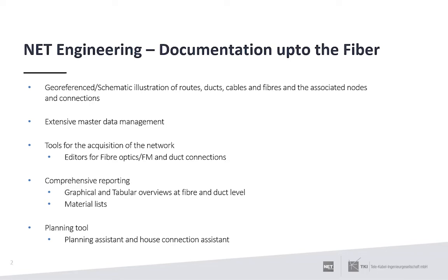You could expect tools for the documentation of the network, such as the connection editor for fiber optics or telecom cable, or the duct connection editor. An extensive reporting with graphical and tabular overview on fiber and duct level gives you an overview of the captured network. A material list can be created quickly from a cluster. Last but not least, the Planning Assistant provides effective support when planning a distribution cluster, and the House Connection Assistant when connecting a single house connection.